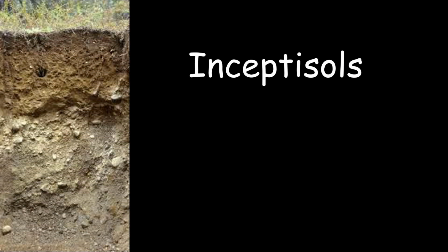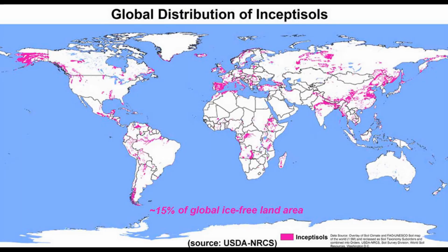We've made it to the baby soil order, or inceptisols. The most common characteristic of this soil is that the inception of a B horizon is evident. Well-defined profile characteristics of soils thought to be more mature have not yet developed in this order. The epipedon in most inceptisols is an ochric, although plaggen or weakly expressed mollic or umbric epipedons may be present.